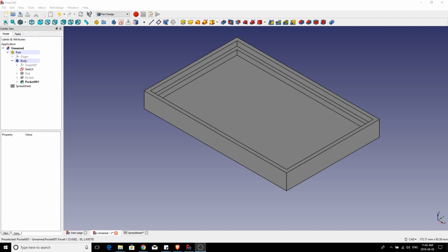There are actually plugins for FreeCAD which will allow you to output your STL or even G code directly, but I kind of prefer to do a step-by-step approach, simply because FreeCAD is in active development, and I don't really want to rely on a lot of plugins in FreeCAD. I'd rather use separate tools for some of the steps, like slicing my STL into G-code. So let's just do this step by step.